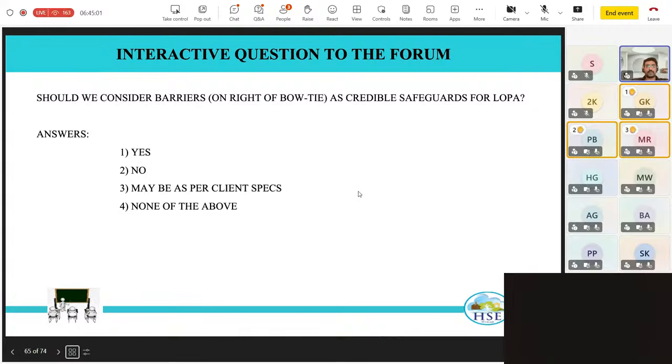And then we were able to demonstrate it. Otherwise, without that, we were actually going into the SIL 4 region, which would have required full redesigning of the full facility. So that is a good example where we can demonstrate that these mitigative barriers can also be considered as protective barriers as long as they are configured to do the protective action.